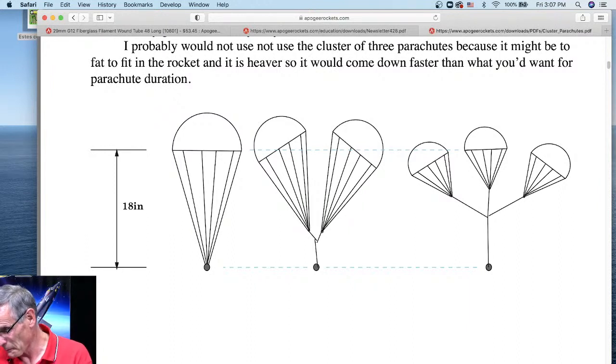I could guess, but you want accuracy, and I can't give you that because everything depends on the shape of the parachute you use, whether it's an octagon, a circle or a hexagon, the fabric, and the length of the shroud lines. All that makes a big, big difference for calculating the coefficient of drag.